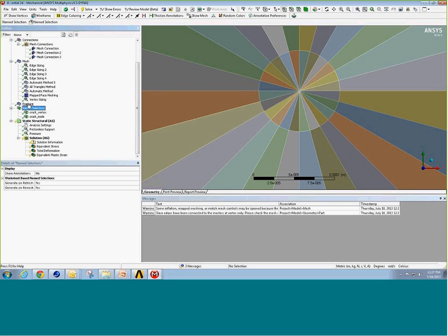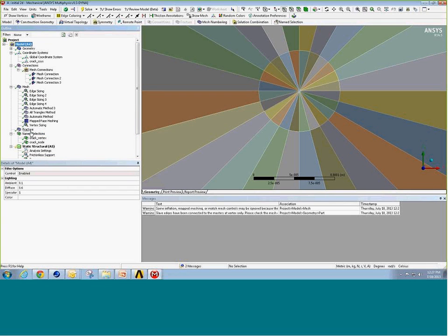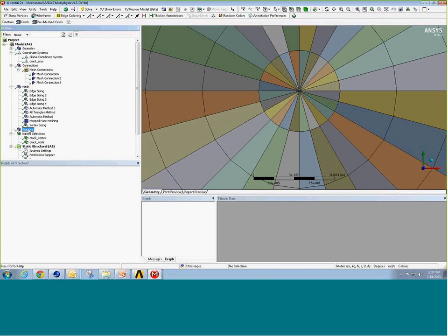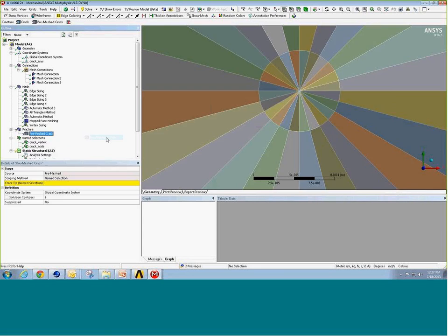So at this point, you can either enter under Model and insert fracture. We already did that, so the fracture tree structure is already there. I'm now going to right-click on fracture and insert. You have two choices, a pre-mesh crack or you want to create a crack. This is a pre-mesh crack. We brought the crack in with our model. So I'm going to use pre-mesh crack, and down at the bottom, it wants to know where the crack tip is. It wants a name selection. I give it the crack node, so that tells it where the crack tip is.